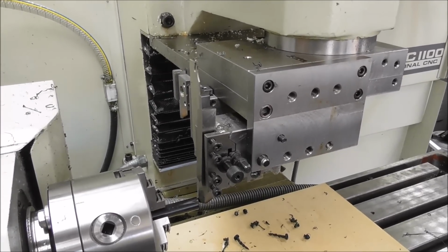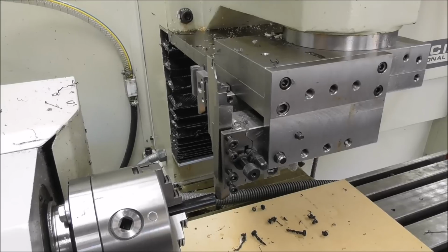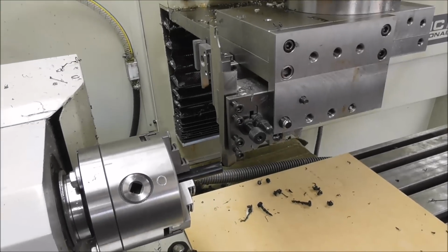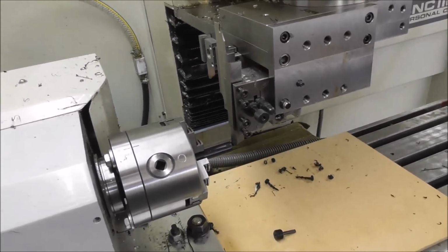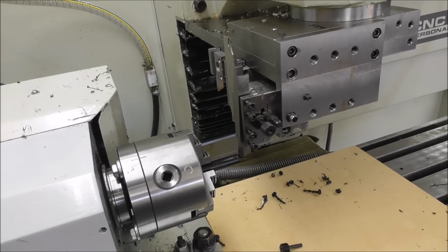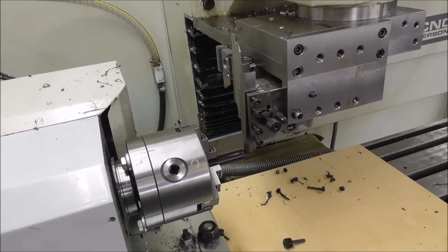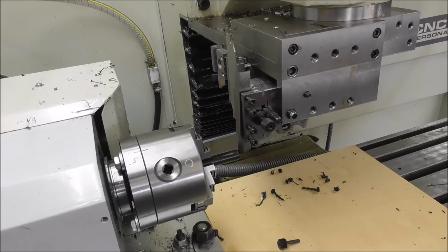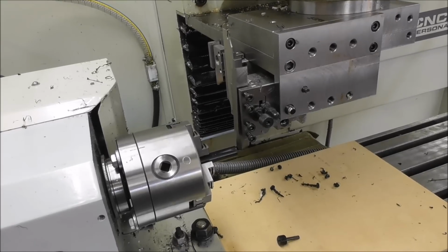And the machine will be making a lot of noise, so I won't be able to talk over it very easily. So I'll just explain now what I'm going to do. It's the transition from one tool to the next. When you're rapiding out from the part, or when you're rapiding across in the Y to the next tool, that's when there's most likely to be a problem. Once you're underway on the tool path, you can speed it up and you'll probably be okay.